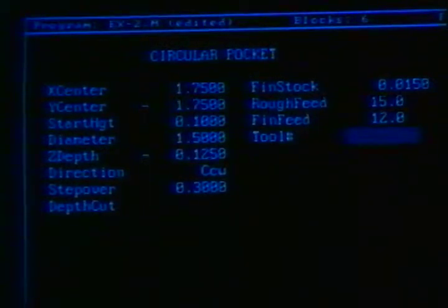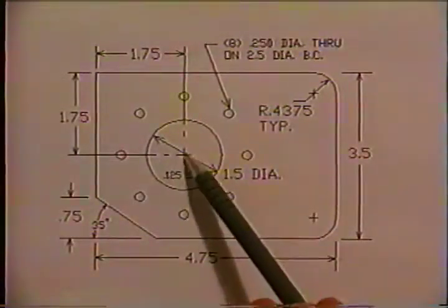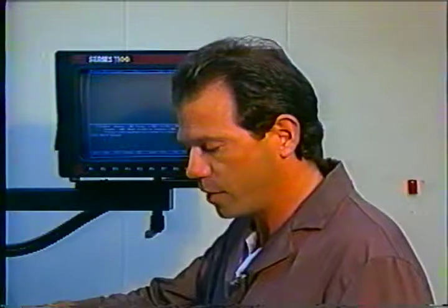And on this entry, we'll also fill in tool number 2 to activate that. We can press the save key. The block is input into the program. At this point, the pocket will be completely milled, and the tool will finish up directly above the center of the pocket. And the next step will be to make a rapid move off toward the upper left corner.